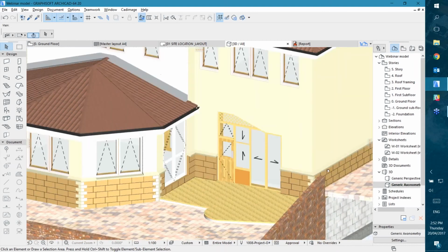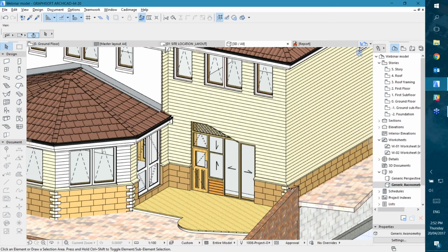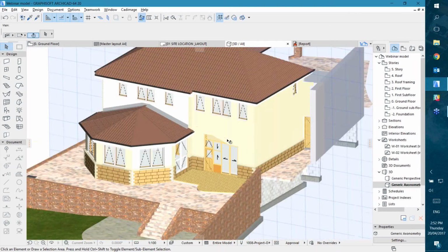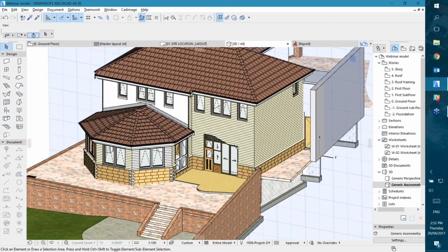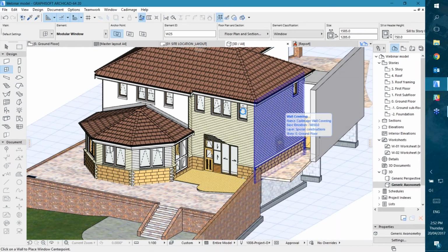We've got a, whatever the word is for that thing, the external corner setting there is applied to the bottom but not the top, which looks great. And again, because these are attached to the underlying elements, if I was to modify any of these wall shapes, or if I was to pop in a new opening to any of those, it will, let me just do it while I'm saying that, it'll let me do that. Except that I can't do it in 3D because it's not getting the wall.